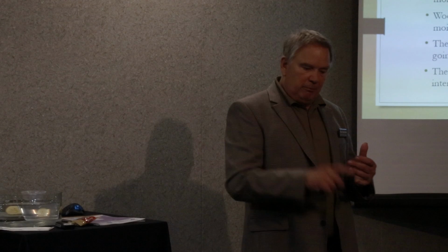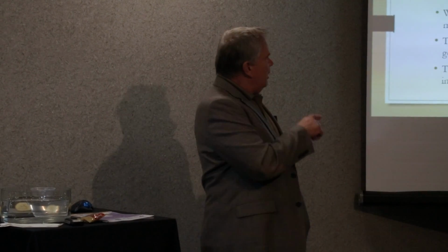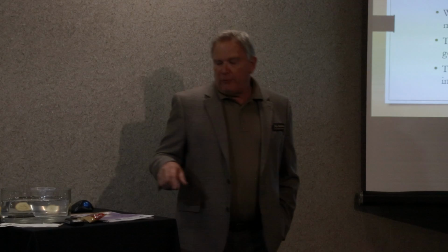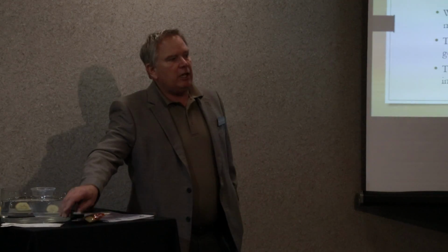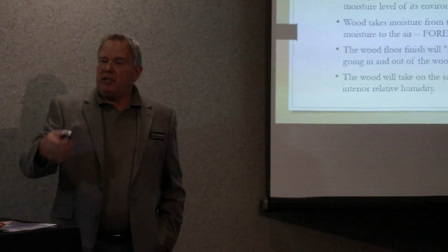It's the same thing when we take engineered flooring out to a job site that's got, like the one in Jersey, 80% relative humidity, and it's there for 6 weeks. The minute that the box is opened, we're in a bad environment, and that thing is sucking up water until it reaches equilibrium. Like it says, it will take on moisture from the air forever. This is a thing we're guaranteed will happen. Our position is to make sure we have guaranteed air.